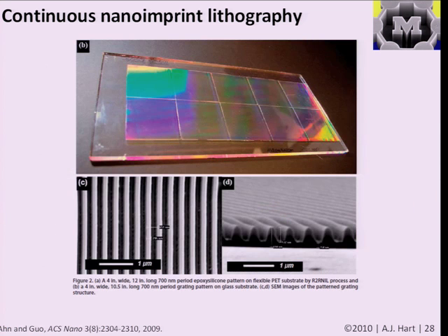And for example, they showed that it can be used to print these kind of submicron gratings. This is about a half micron by a few hundred nanometers on polymers that are on glass plates over pretty large areas. So I think it's a really nice result that shows the potential of this technique to do things rapidly and scalably. And innovations in this technique will, certainly, if you can take these features and align them with lithography patterns made by other methods made in other materials, as we saw from the roadmap, this will complement our existing directions.